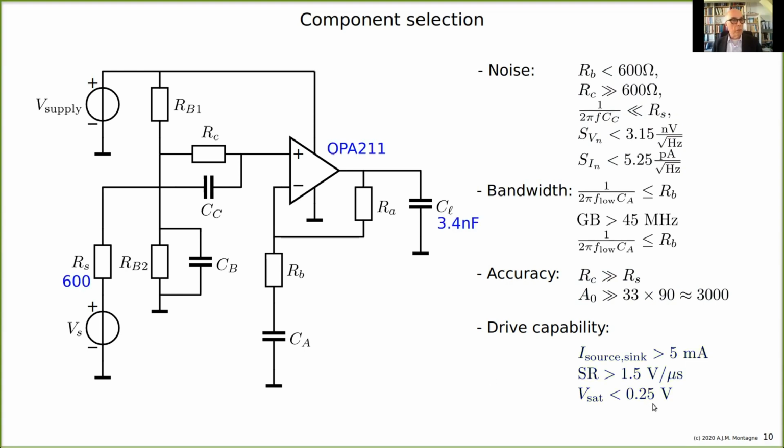And then you go to the internet, you go choosing, and you see I did something. I selected the OPA211. That is an operational amplifier that we have done before. And of course, you can select many others. I just wanted to do this one because this one has a very complex output impedance that causes all kinds of nasty effects with this load impedance, and still we can get it stable and give it a nice step response.